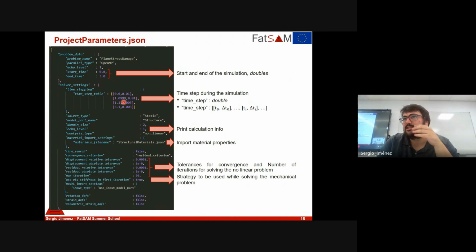Yes, the restart is also implemented in Kratos, but if I'm not wrong, by default you are creating post-bin files as post-process, and I think that you should move to ASCII post-process files, because then you should be printing a specific kind of information to then be able to relaunch the model from that specific point. But I'm not that familiar with the restarting. But it's something that is available in Kratos.